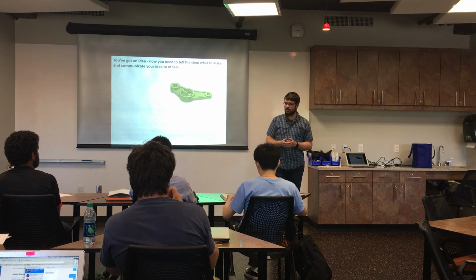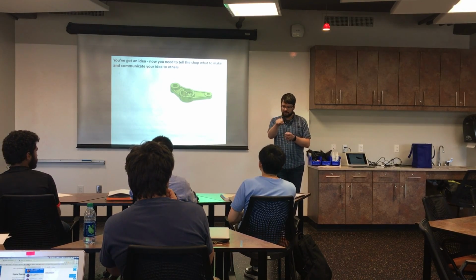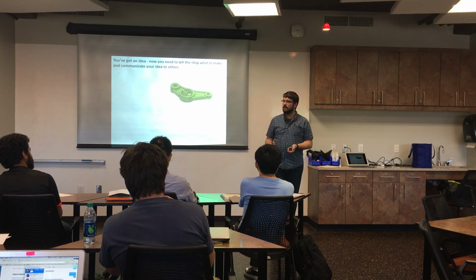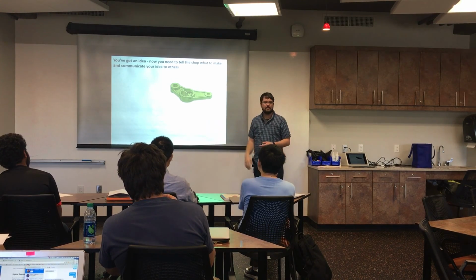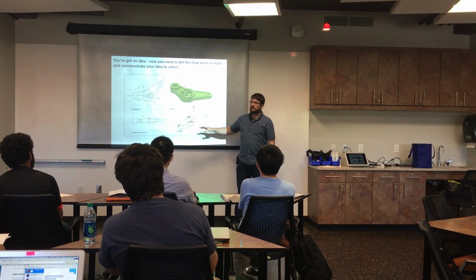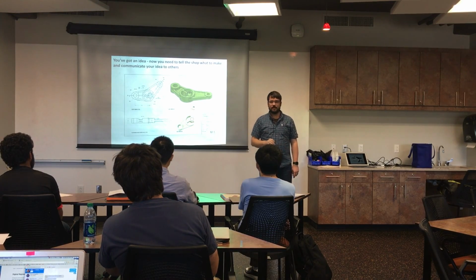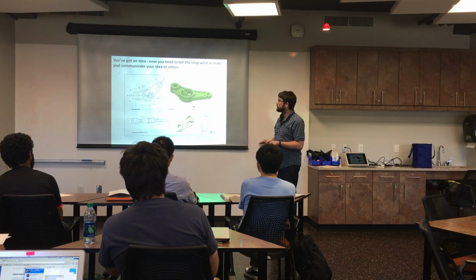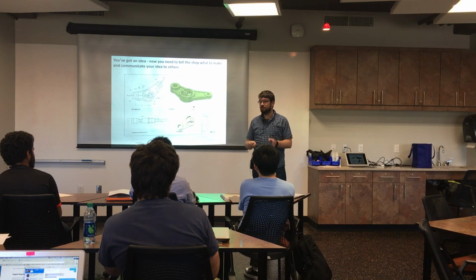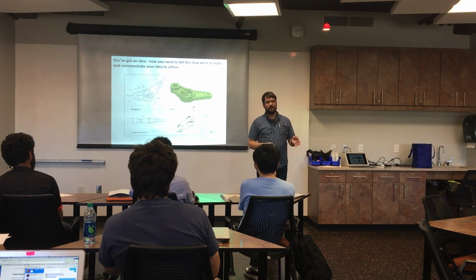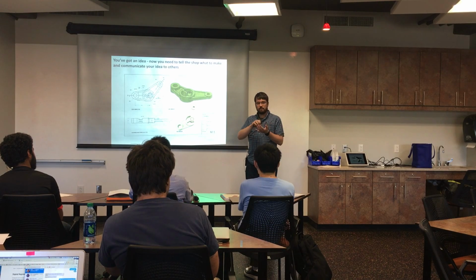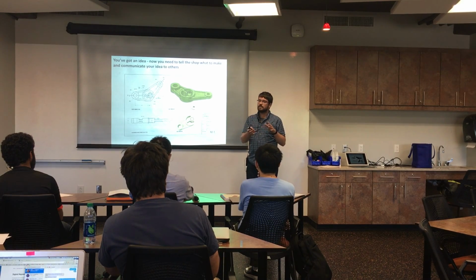If you sit down over at the machine shop and you pull out a piece of paper and you say, well, it's square, it's got this angle on it about 30 degrees or so, they're not going to do it, and Ellis will look at you like you're crazy. What they need is a mechanical drawing, something that fully specifies every dimension, every part about the shape of the object. And we're going to go over how to do this by hand, so some basic mechanical drawings today. And then next week, we're actually going to use a CAD tool, and we're going to be able to model the part in 3D in the CAD on your computer.